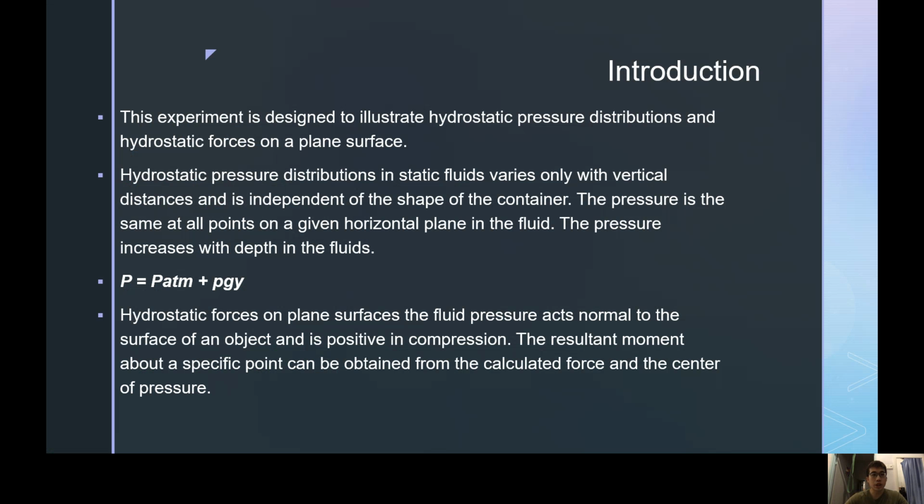The introduction. This experiment is designed to illustrate hydrostatic pressure distributions and hydrostatic forces on a plane surface. Hydrostatic pressure distribution in static fluids varies only in vertical distances and is independent of the shape of the container. The pressure is the same at all points on a given horizontal plane in the fluid. The pressure increases with depth in the fluids.